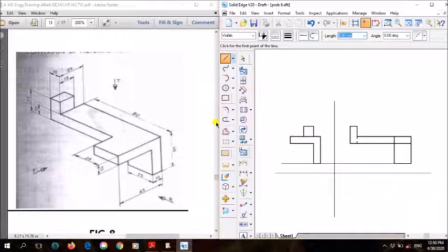Okay, so like this, in right view this surface is visible and this surface is visible, we have drawn. So now what are the surfaces which are not visible, right? Whatever this projection is there, just concentrate on the left side of the screen, the cursor. This projection is fully a solid projection of height 25 and width 15. So height it is 25, but we have only drawn how much? 15 mm. So 10 mm is what? It is lying beyond, or behind this solid, right? Behind this solid. Hence this remaining 10 mm is not visible.